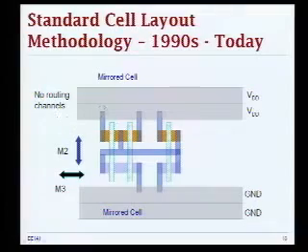Even if you have, for example, transistors implemented, a pull-up network over here for the N well, you can extend that N well all the way to the boundary of the cell, such that when you put together the next cell, all these diffusion areas will be continuous. You have just one nice piece of diffusion, and you have really extremely high density. And then I will show you how you can utilize this graph-based approach to construct cells of highest density.